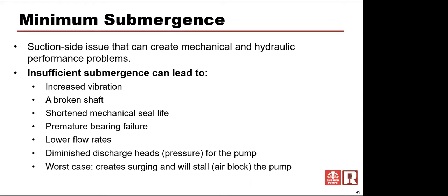And when you draw water out of a tank, or you have a vertical pump mounted down into a tank, when the liquid level gets low enough, we can suck air down through that water. A common example of that is in your bathtub. There's a velocity of water going down through a pipe, your drain, that's drawing water out of that bathtub.